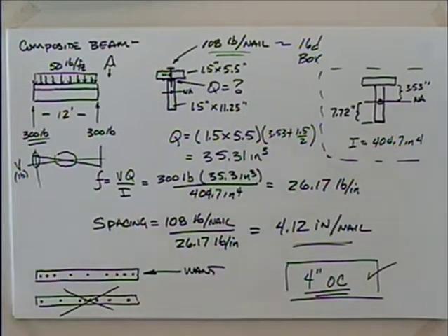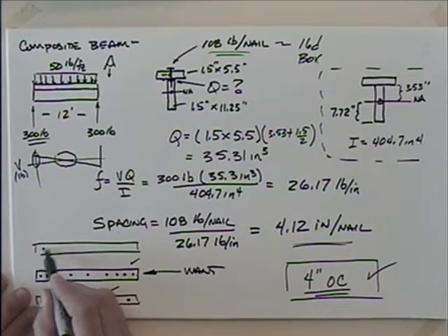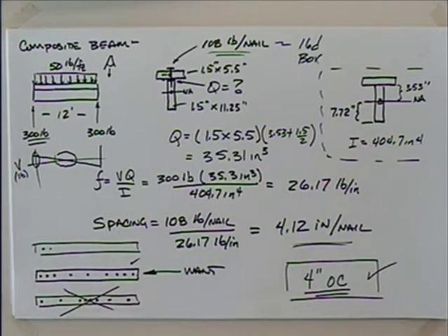I mean, if this is something where maybe we're using a robotic nailing system or something, and we're going to be the ones programming it, this is probably just fine. If we're trying to rely on people to do it, maybe we're going to have to make a template. We make a template, and we drill the holes in this template where they should be, and just have them lay that on there, run a strip of spray paint down it, and then they mark where the nails go or something like that, right?